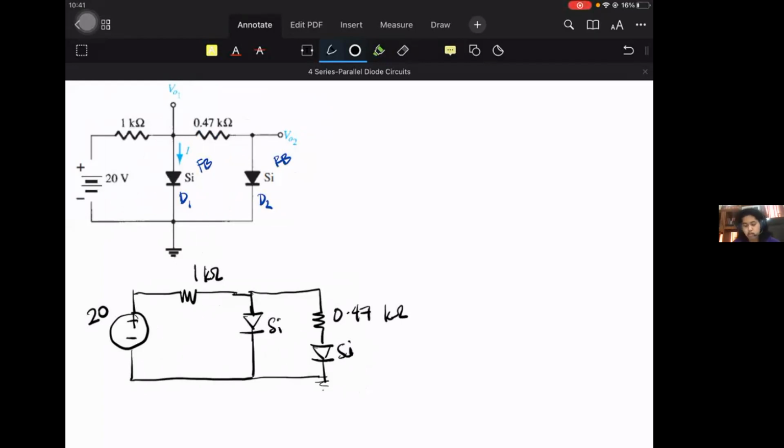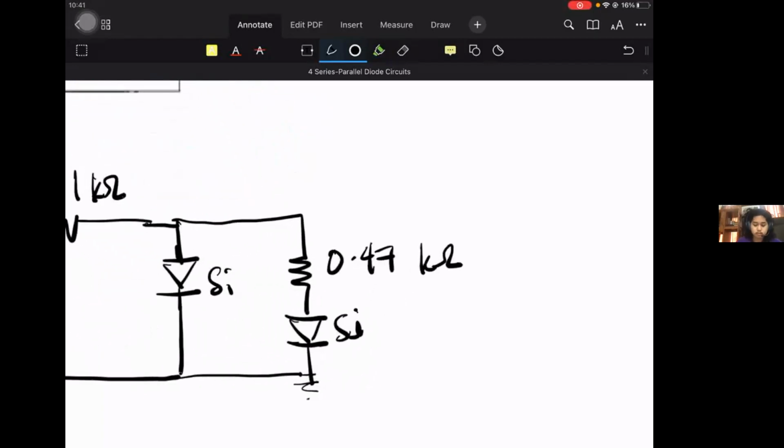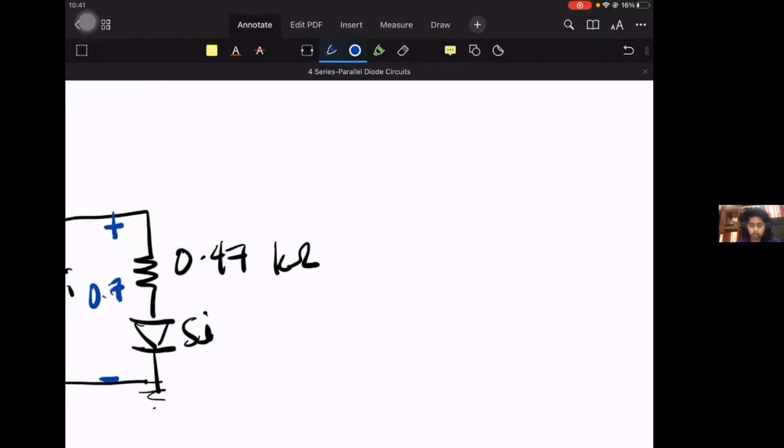So by virtue of parallel circuits, the same, obviously, this is the motor, okay? So 0.7 volts is the drop in this first diode. Because they are both parallel circuits, this is supposed to be 0.7 also, right? For it to hold true. Now, is this second 0.7 enough to turn on the second diode?